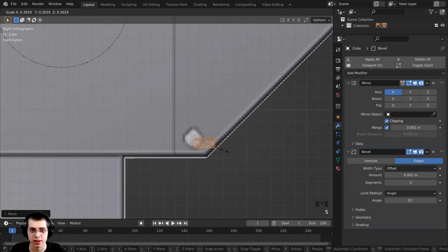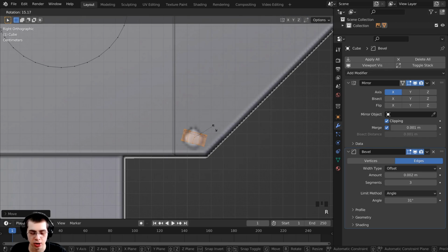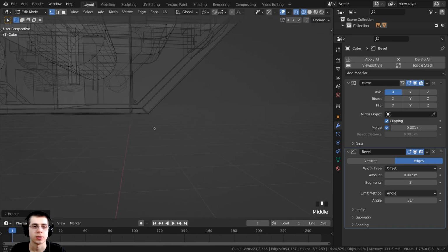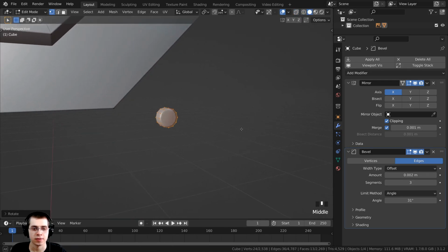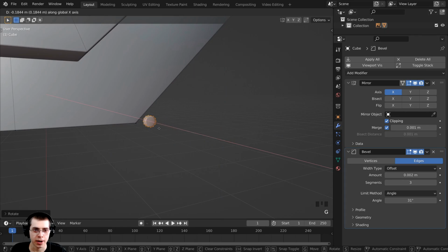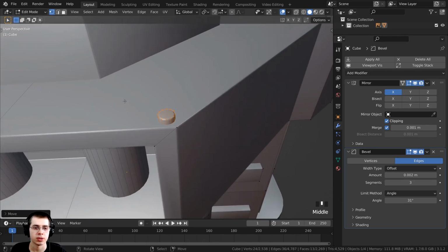and then I can press S to scale, G to grab, and then I want to rotate this bolt over, so let's press R to rotate. I can rotate it on the Y-axis, and then I can type 9, 0, and enter, just to rotate it over by 90 degrees. Hold down the Z button, go back into the solid view, that looks good, and then I can press G to grab, bring it back on the X-axis, and just stick it right in here. Place it there, I can press the period on the numpad to zoom into it.